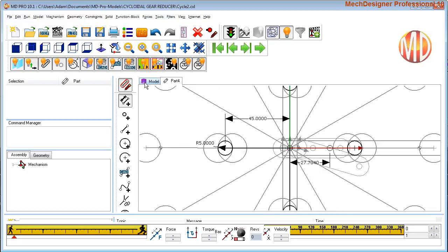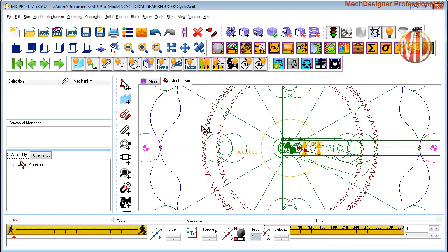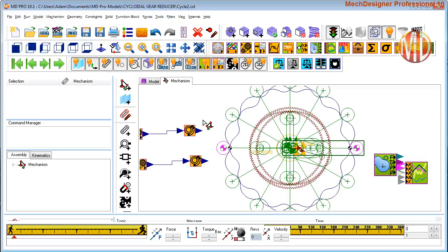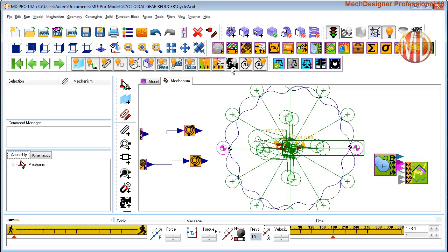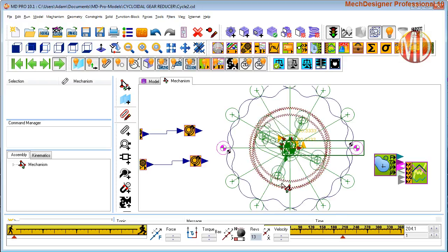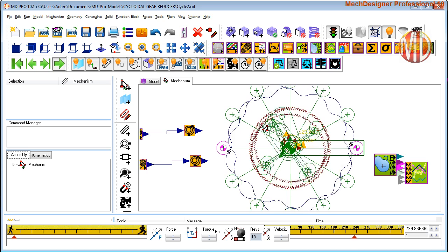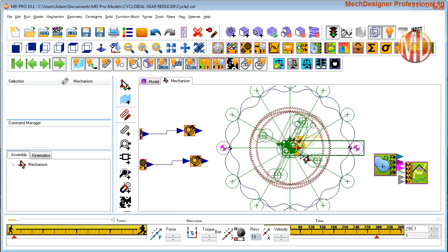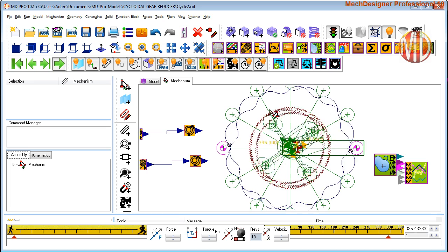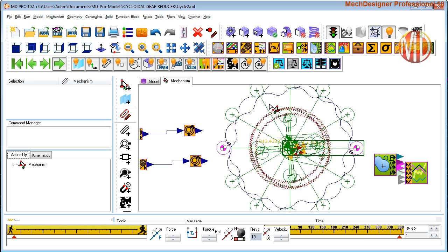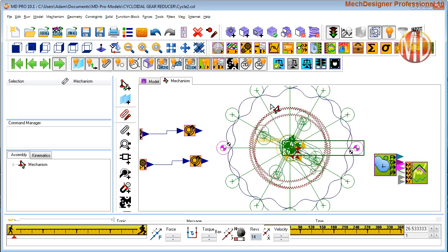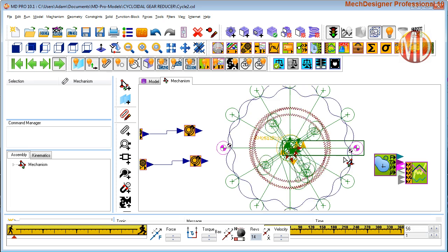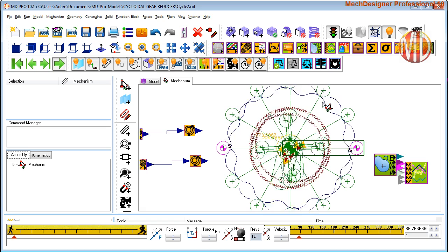Okay, so that's the kinematic design done, so all the parts are in place. Incidentally, the gears are used only to develop the type of motion that we need in order to generate the motion of the wobbling parts, which are the lobed rotors, and by virtue of that motion from the gears we can generate the cam profile.